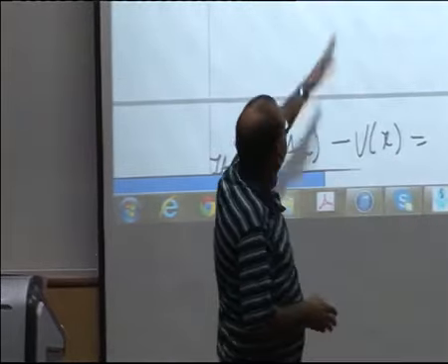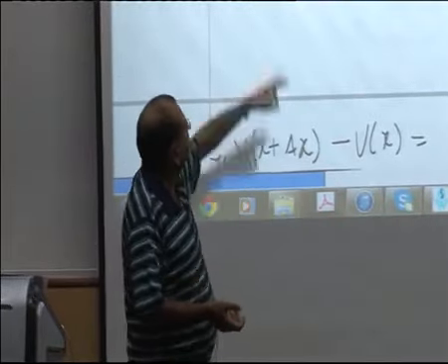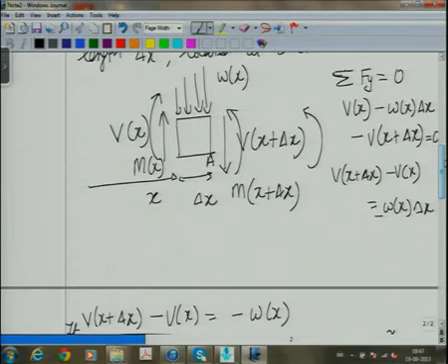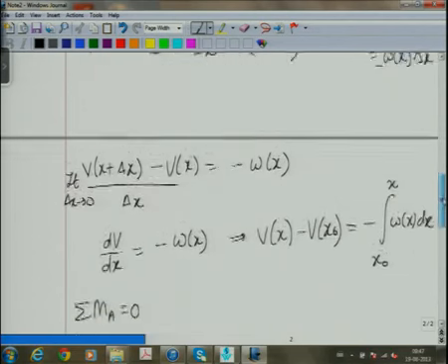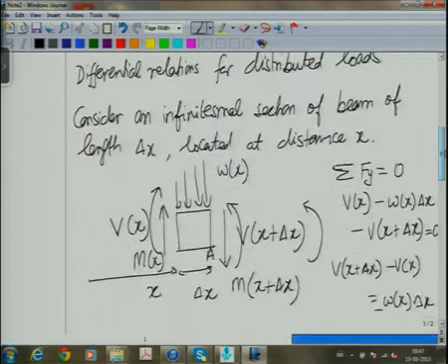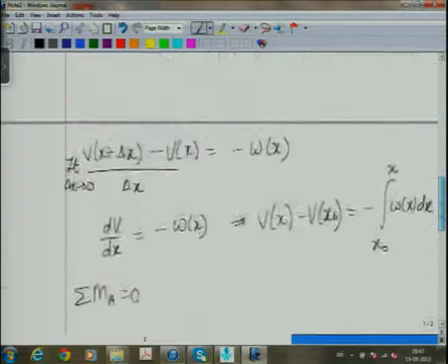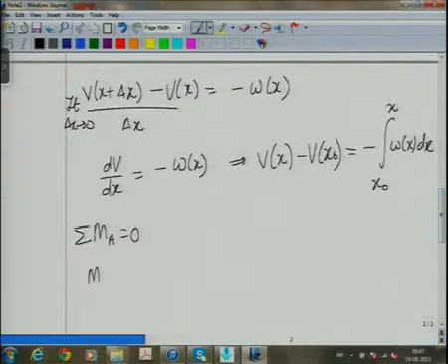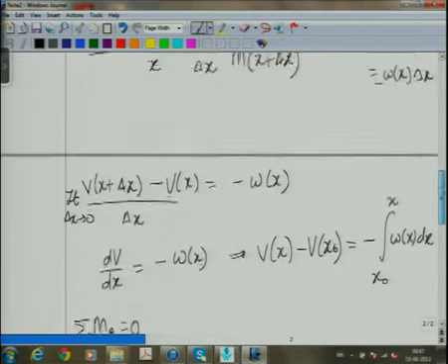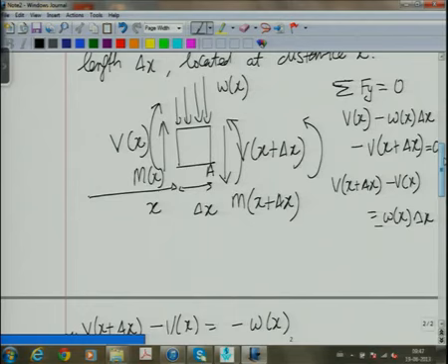So that's why I choose, let's say, point A. So when I take moments about point A, what do I get? Firstly the two moments will come as they are, M at x plus delta x minus M of x. These two terms come from the two moments.